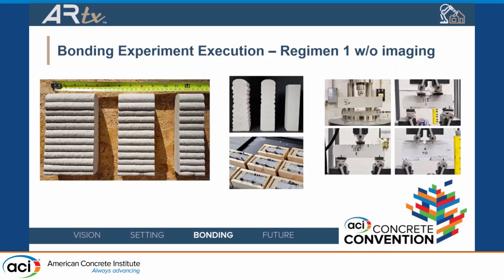So right now, the prevailing method for testing these is ASTM E518, but there's still a lot of unanswered questions about how to use that for 3D printed concrete with regard to uniformity of bearing conditions, load rate, et cetera. So we chopped these up into different widths. We did different kinds of profile treatments, capping, trimming, and working with just natural printed profiles. And then we broke these in 4 and 3-point bending.